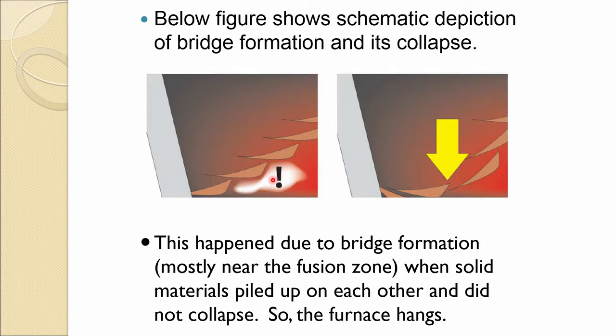Now, this figure shows some of the phenomena. I think we talked a little bit about the slipping or hanging. We talked in terms of when the upward forces are greater than the downward forces, the material will not descend, hanging may occur, and we said a few causes of it.